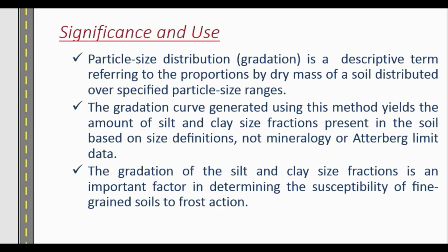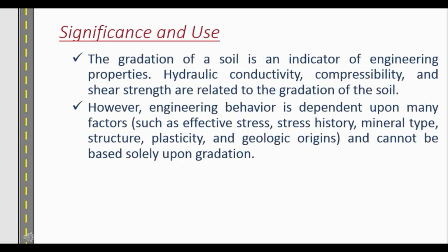When we have to classify the soil, we need the amount of silt and clay particles present in our soil sample. For this we have to determine the amount of silt and clay for classification purposes, and for other engineering properties like hydraulic conductivity, compressibility and shear strength.